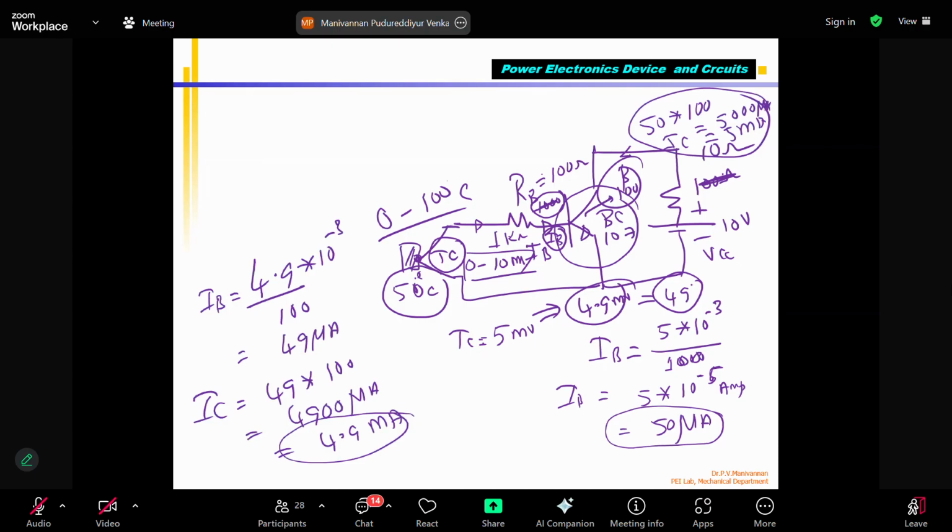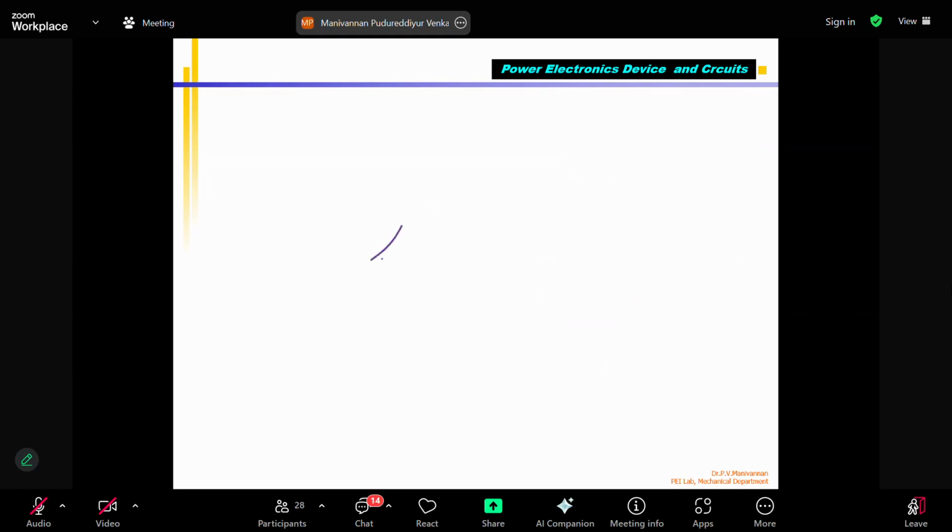Also, because of the loading effect, the sensor voltage is reduced by a small amount. This is called a loading effect. So that means if I use a transistor amplifier, which is a current amplifier, right? Transistor amplifier is a current amplifier. Loading effect is there. Instead of that, I take my same thermocouple and connect it to my FET.